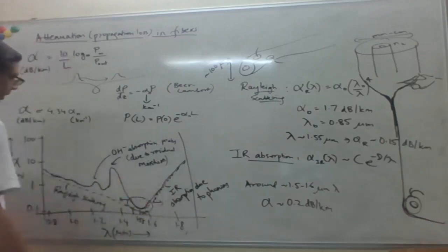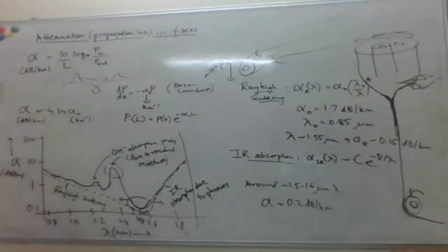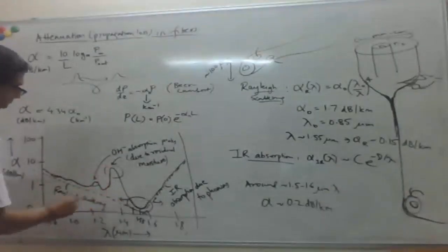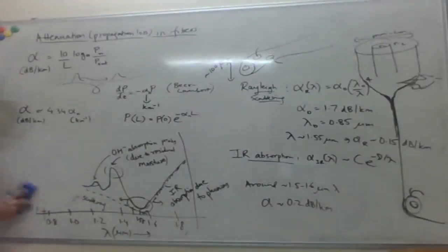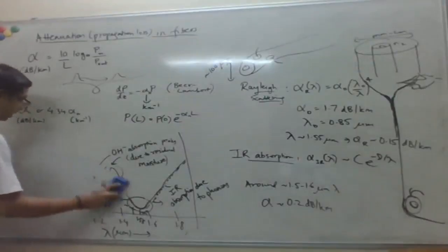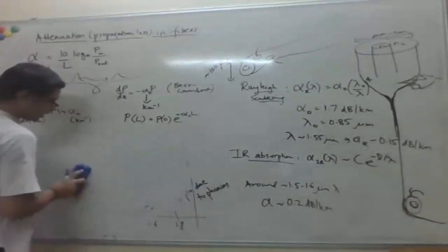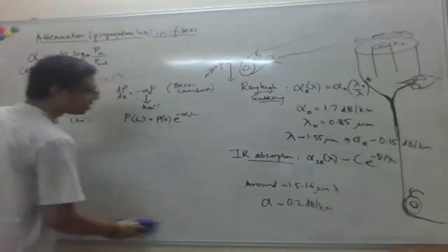This is fundamental, right? But here these peaks are not fundamental, as I said, they are due to residual moisture. So if you could somehow get rid of that also, then you can suppress these peaks and then go towards shorter wavelengths. Okay, so over let's say the last 10-20 years, people have also figured out how to do that. So these big companies which make optical fibers like Corning and Lucent, Alcatel, have figured out how to make what are known as dry fibers, okay, without any moisture.